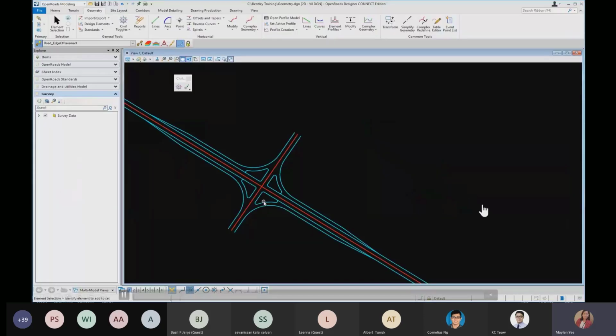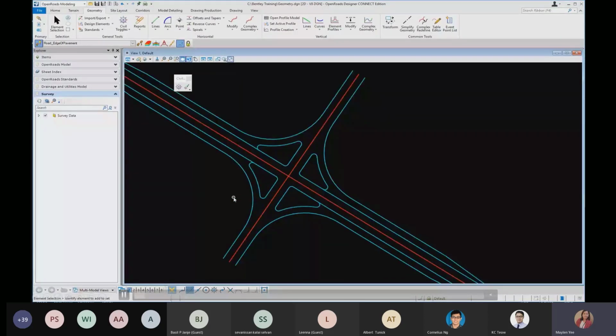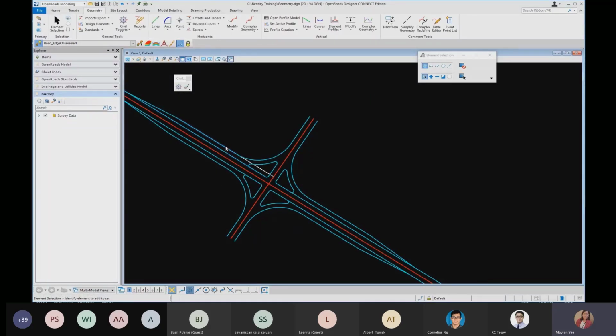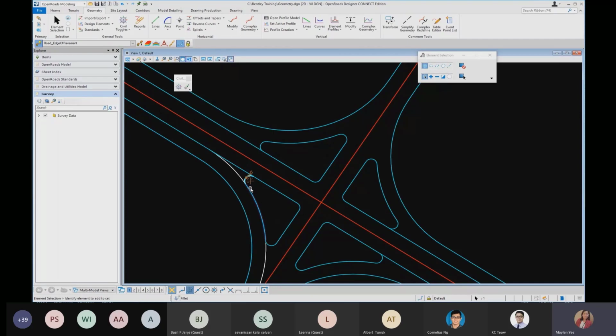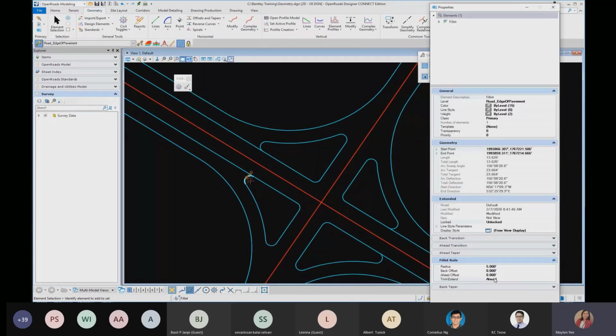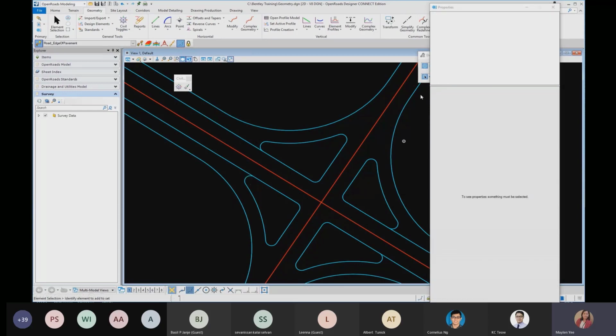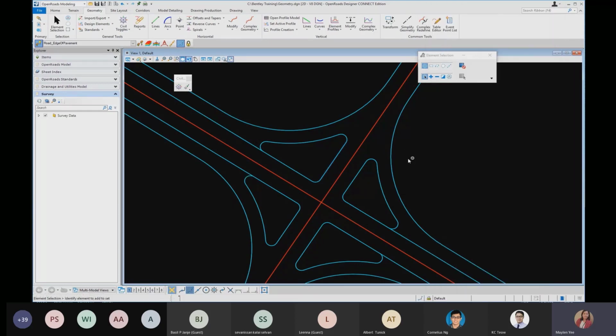And anytime, like for instance in this example here, if you're done with your geometry, and any element, in this case the horizontal alignment, needs editing, you are sure that you're getting the right information because the object itself preserves your design intent regardless of where you are in your design workflow.